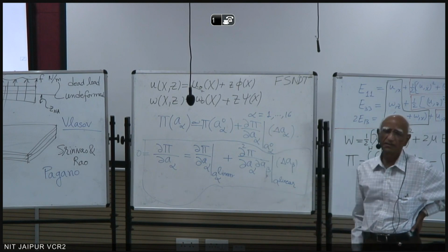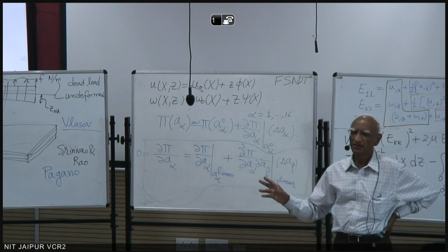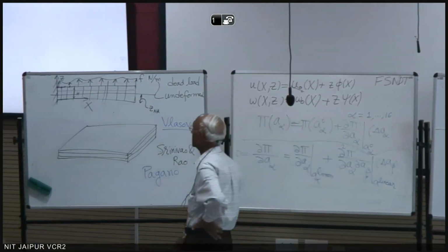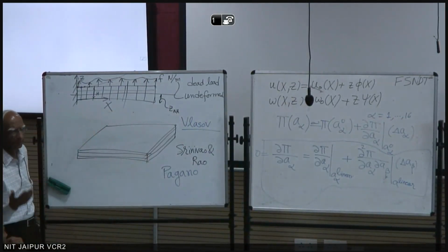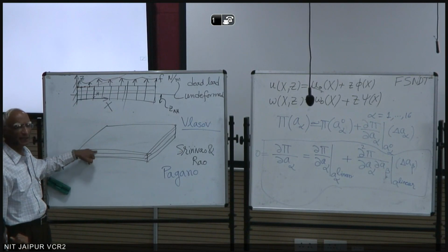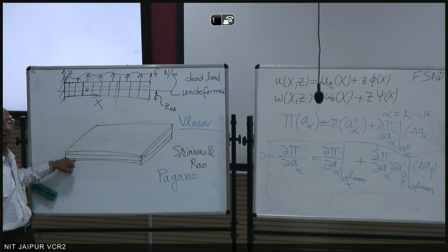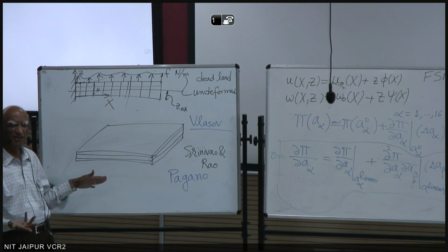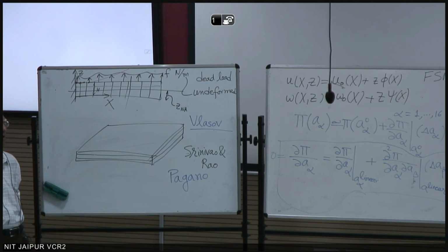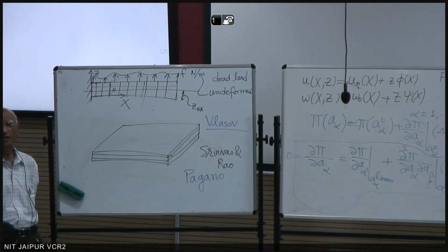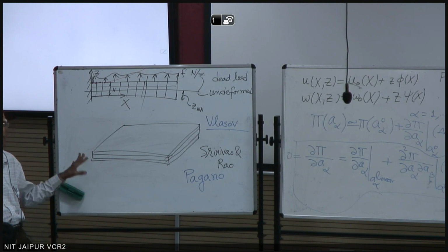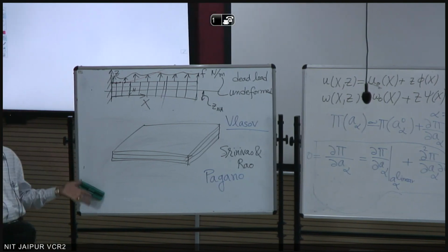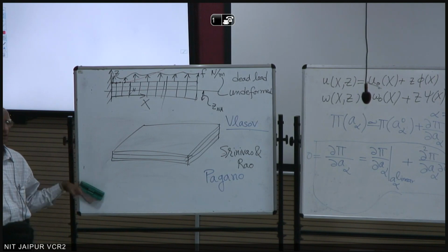Then, of course, he extended that to many cases. Once he did it for a clamped plate, he could do this edge clamped, this one free, this one with a different boundary condition. So each layer could have a different boundary condition, which, if you try to do it numerically, finite element, Abaqus or LS Dyna may not like you very much. But analytically, he could do it. And he did it for a functionally graded material. Then he studied vibrations. His work is very well cited, Senthil Vale.